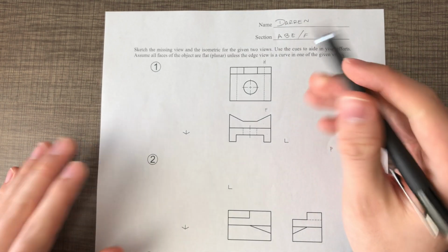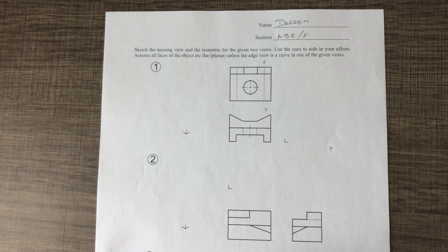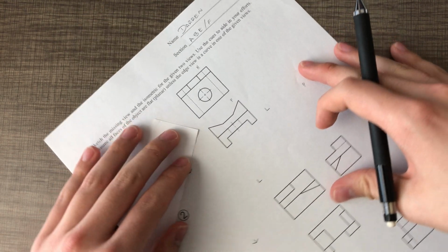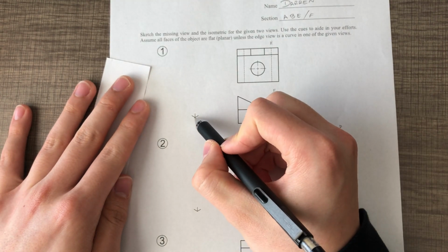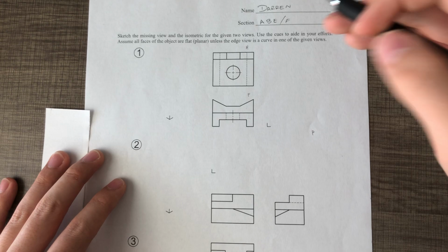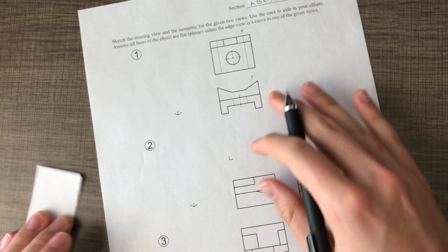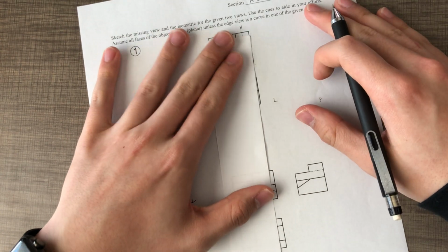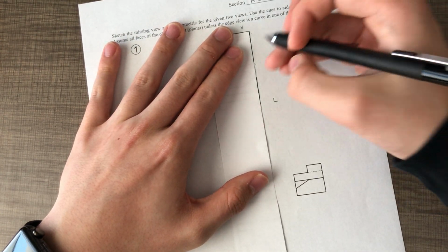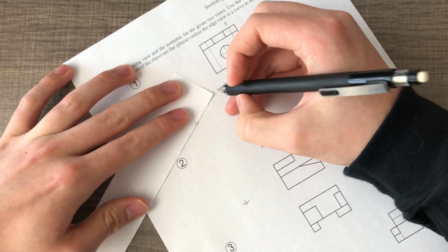Looking at it like this, there's a very simple way to visualize it, and let's start by drawing our isometric bounding box. So first off, if I want to get this dimension of my bounding box over here, figure out how far this goes, that is going to be the same as the height of my top view. So let's trammel that distance over here.